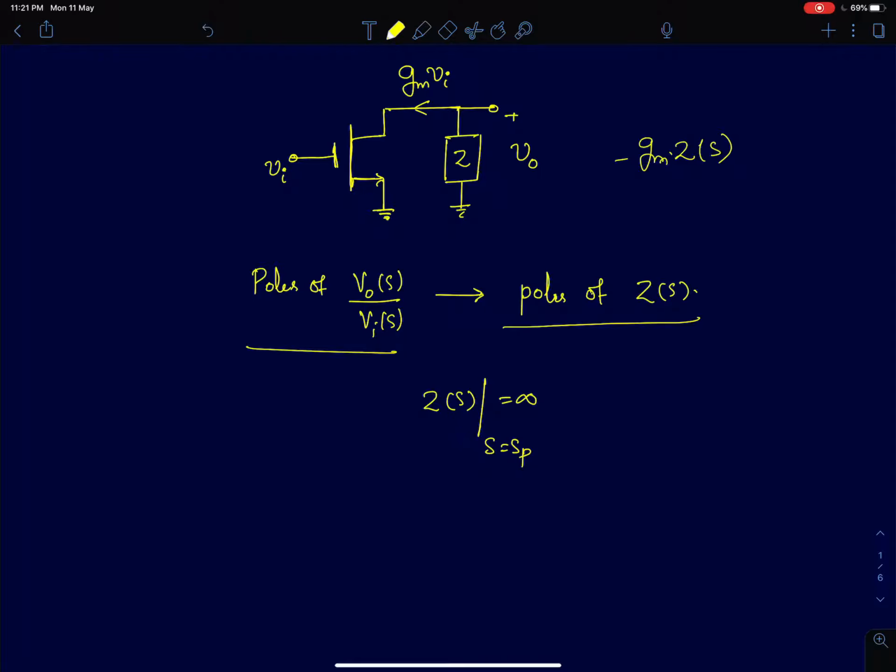And then we said we can find the frequency response by evaluating the transfer function at s equal to j omega. Now once we know the frequency response, we know the response of a circuit for any input. Okay, any input which is Fourier series or Fourier transform representable. So that's why finding transfer functions for circuits is of great importance.